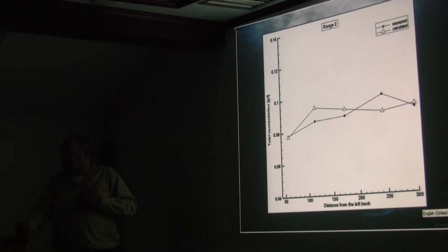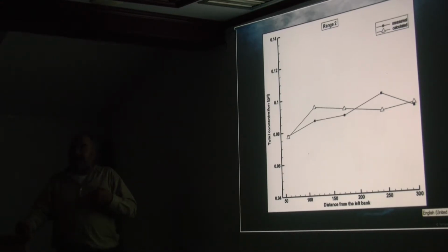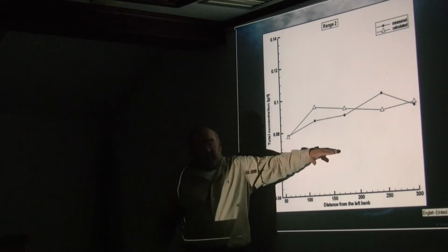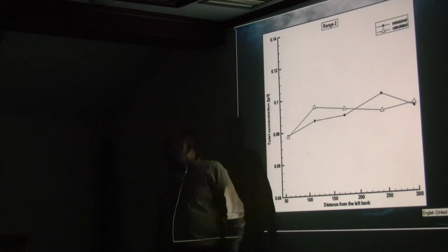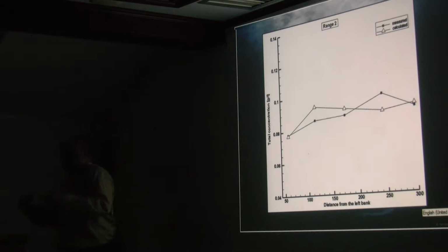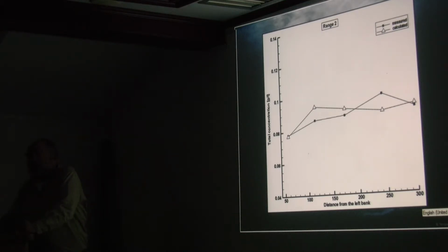If we don't do that, if we, let's say, try with a representative size class, let's say D50, D50 would be here. The improvement is significant. We did that. We didn't have time to put it here, but we did it on some other data sets. And the improvement is significant. It could be on the order of 30 or 50% improvement.